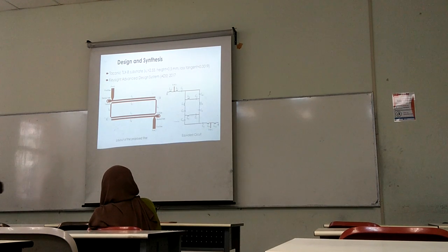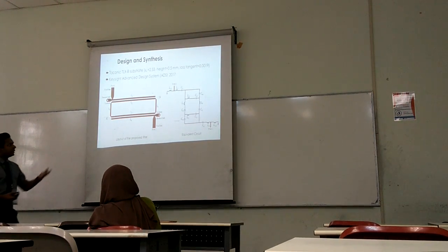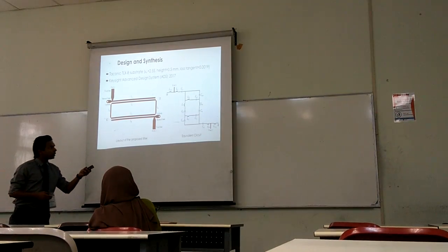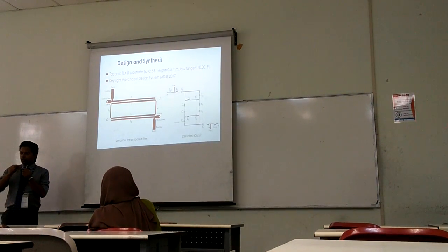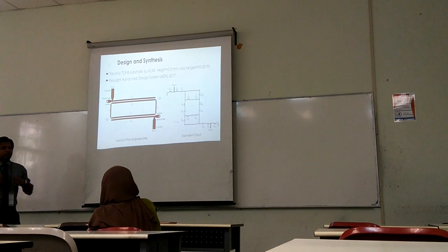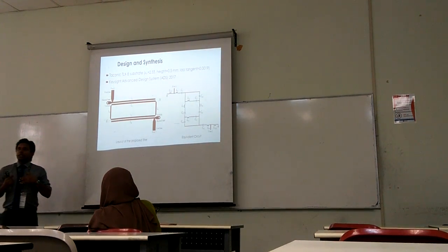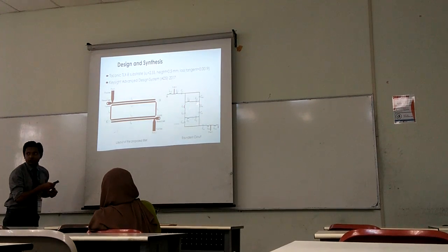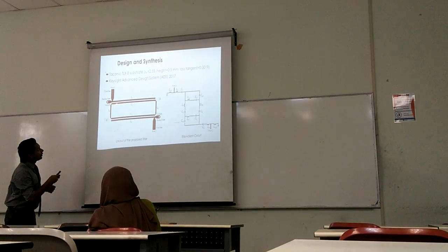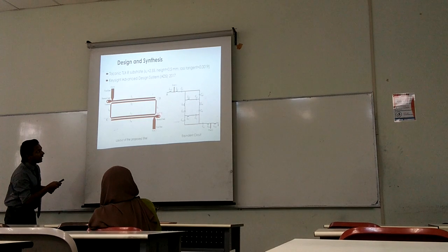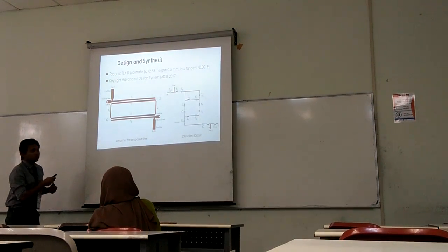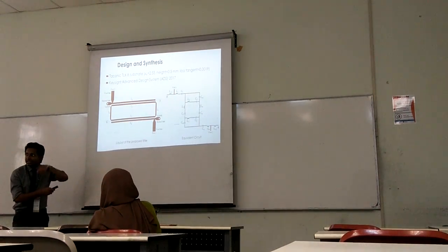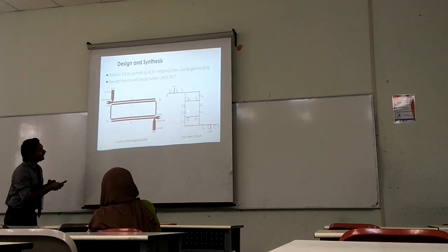And to represent our work in terms of an equivalent circuit, a lossless lumped equivalent circuit, we all know for a microstrip line, if there is no grounding, then it's like a series inductor and capacitor. So in our case, we can see a lot of lines like that, but we have two lines that are connected to the ground. So these only two lines are like only inductors because this is an inductive via. But for the other case, it's like this.